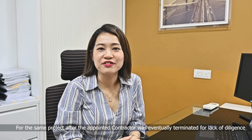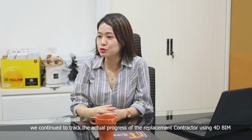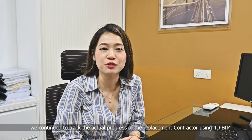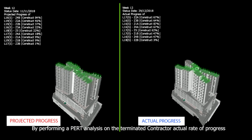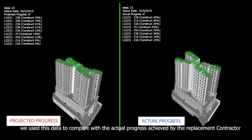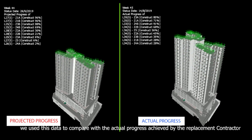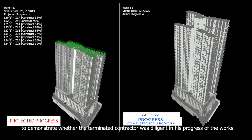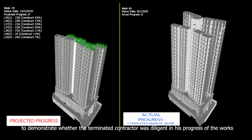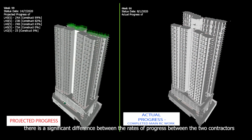For the same project, after the appointed contractor was eventually terminated for lack of diligence, we continued to track the actual progress of the replacement contractor using 4D BIM. By performing an analysis on the terminated contractor's actual rate of progress, we use this data to compare with the actual progress achieved by the replacement contractor. And this was used as part of the evidence in the arbitration to demonstrate whether the terminated contractor was diligent in his progress of the work. As you can see from this analysis, there is a significant difference between the rates of progress between the two contractors.